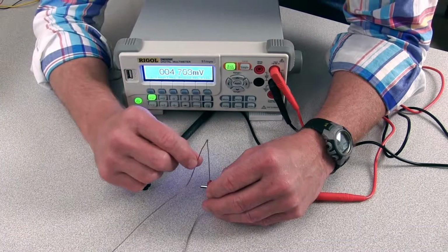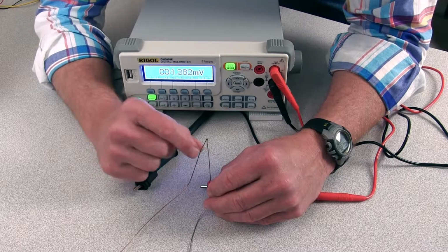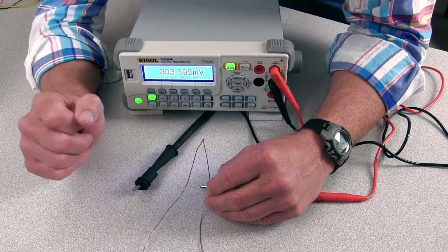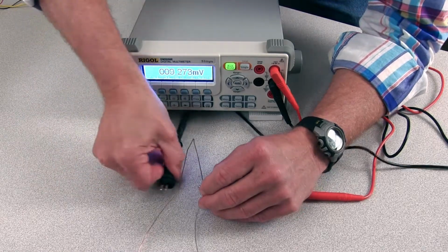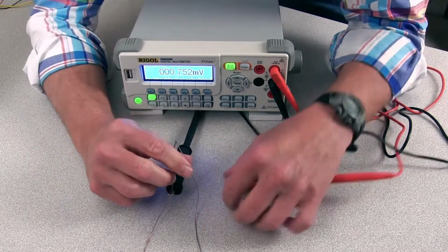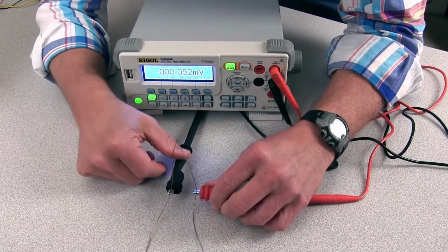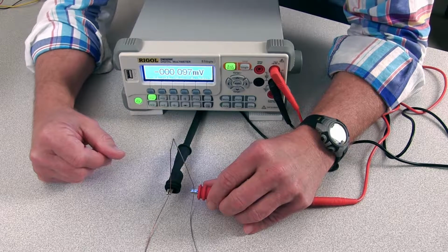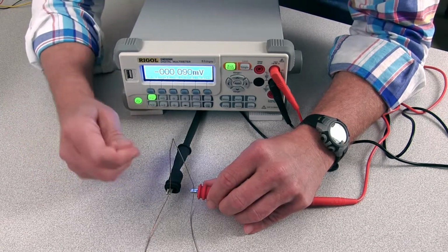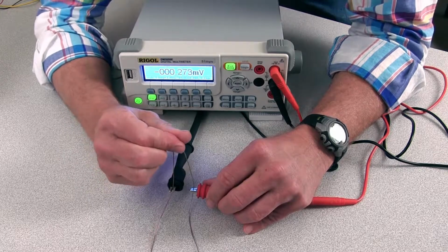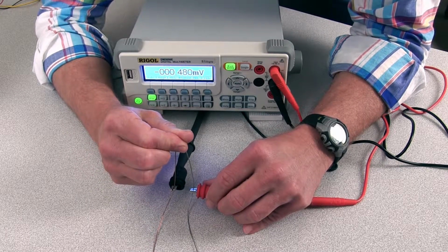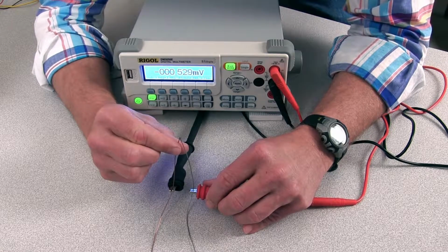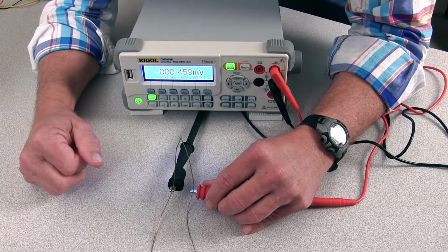This is a thermocouple. All it is, is two different wires made out of different metals that have been joined here. If I change the temperature of this junction between these two metals, I should get a voltage out of it. So let me connect my DMM to measure the voltage across this terminal. I get about minus 0.097 millivolts at room temperature. If I warm this up by gripping it between my fingers, I get up to about a half a millivolt. I do get a temperature change out of this by warming it up. It's just not a very big change.